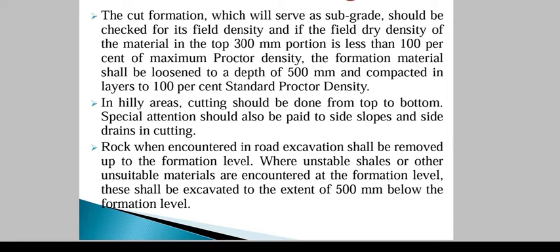By blasting and other means you can do it, but the cost will be higher. It should be checked for its density. If the field density of material in the top 300 mm portion is less than 100% of maximum proctor density, the formation material should be loosened to a depth of 500 mm and compacted to 100% standard proctor density.